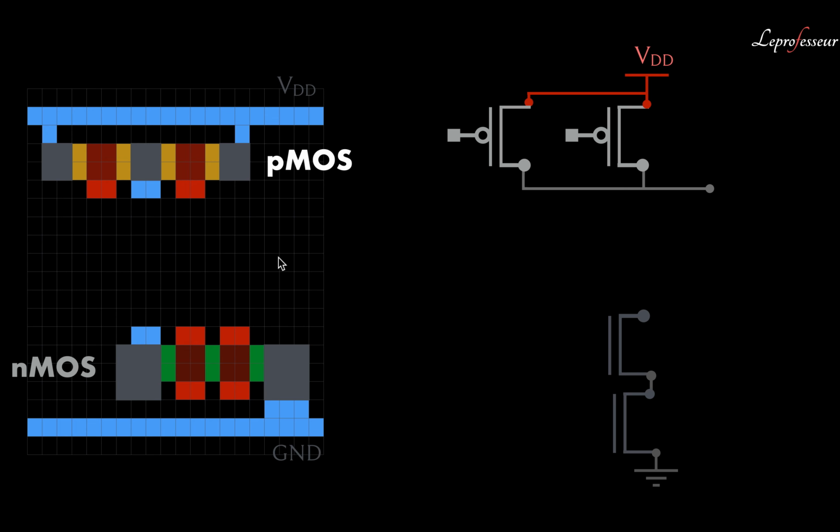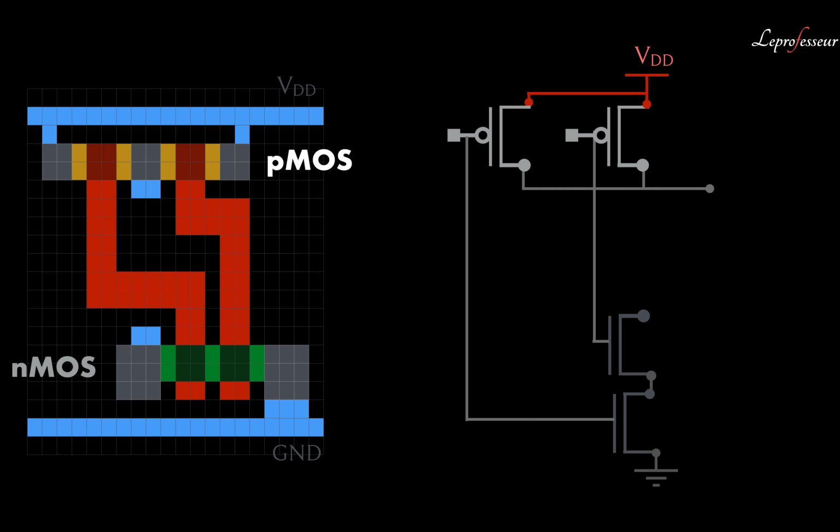Or you can call it rectangle. Important here is not terminology or name what you call it. Important here is to understand the concept that in NMOS, when they are in series, there is no contact in between. In PMOS, when they are in parallel, there is a contact in between. Okay, now let's connect it further. So both the gates of the PMOS and NMOS are connected together.